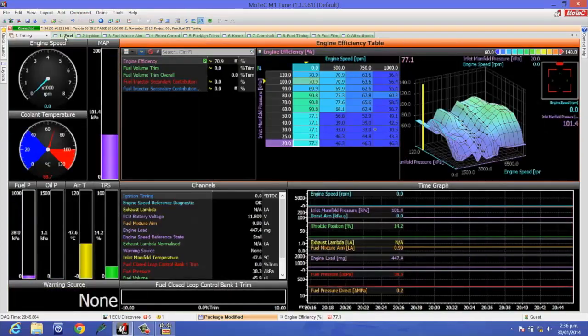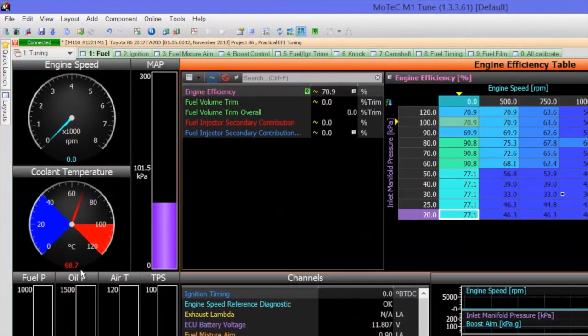As usual, after configuring the sensor, it's time to check that the reading you are seeing is actually reasonable. The coolant temp and air temp on an engine that hasn't been running should measure approximately the same as your ambient temperature. If there's a difference of more than a couple of degrees, it's time to check your calibration.